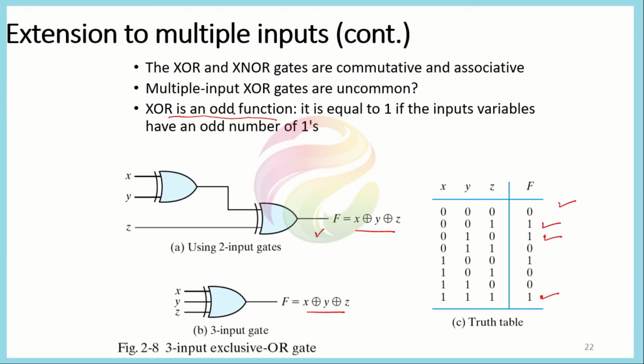So the actual definition of the exclusive OR operation is that the number of ones in the input should be odd. If that's true, then the output equals 1, otherwise it will be equal to 0. This definition is slightly different from the one we studied for the two input system, and it is also applicable for the 3, 4, 5 or further exclusive OR inputs.